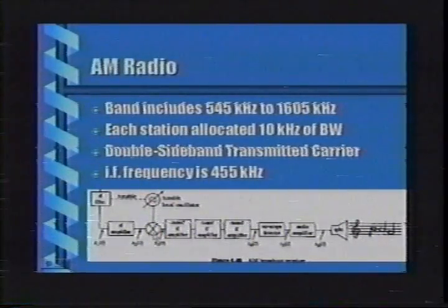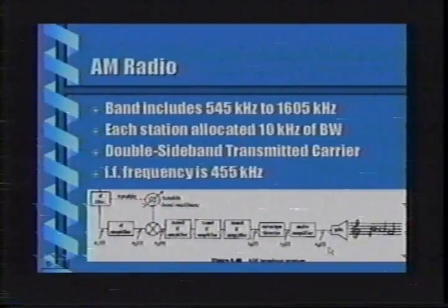We then multiply by a local oscillator, and that's what shifts all frequencies up and down by the frequency of the oscillator. We then go through the IF strip. These are simply typically 3 tuned IF filters that combine amplification and sharp bandpass filtering. We then demodulate with an envelope detector. We do some audio amplification, and we're ready to listen to the signal.